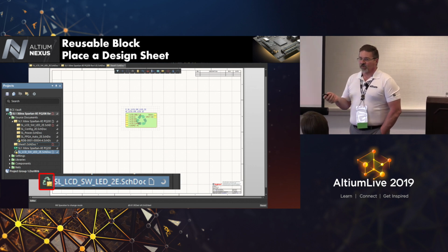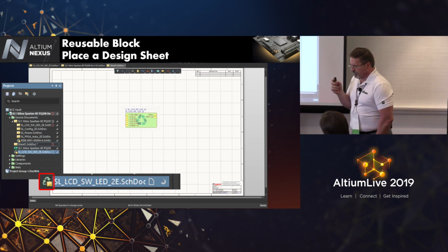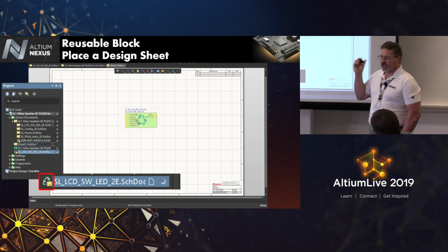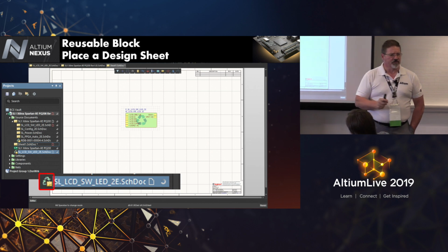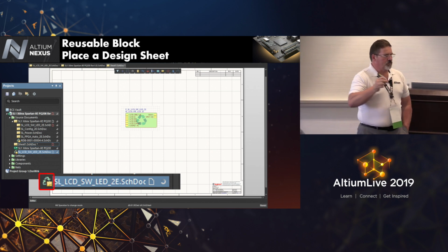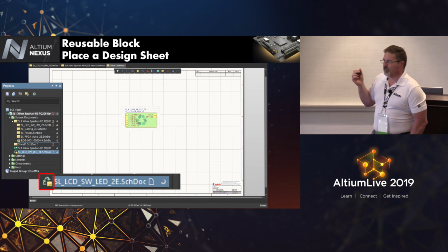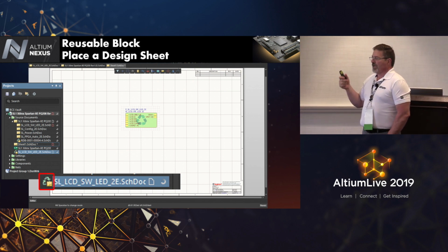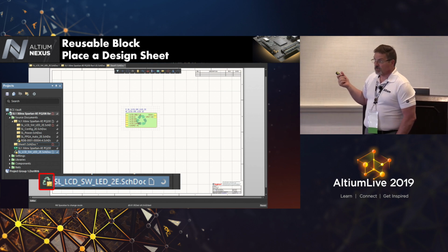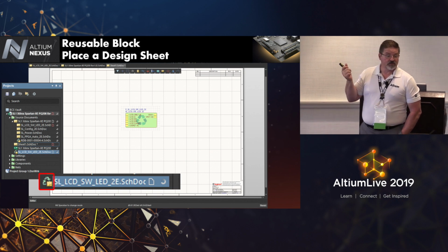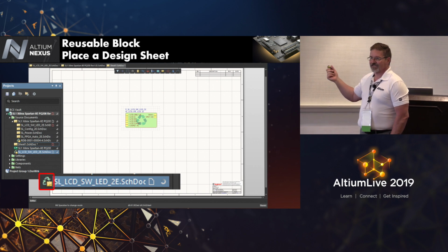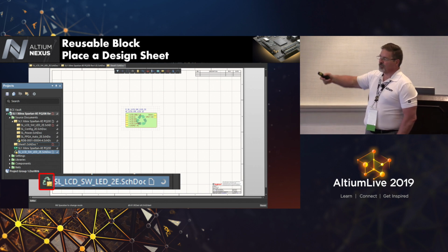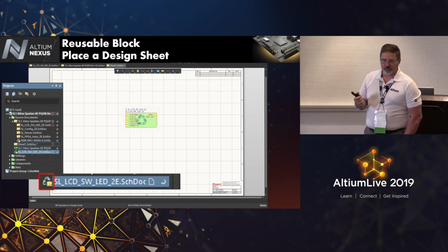Because what we want to do, remember, is time to market, that's being driven into us right now. If we've gone through a high power circuit, for example, and it's gone through UL, we take a snippet of that and we save it off, because that tells us how we designed it, and we pull that snippet in the next time we use that circuit.